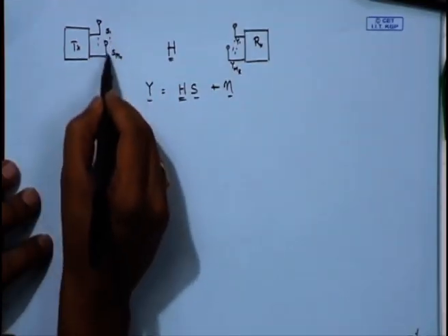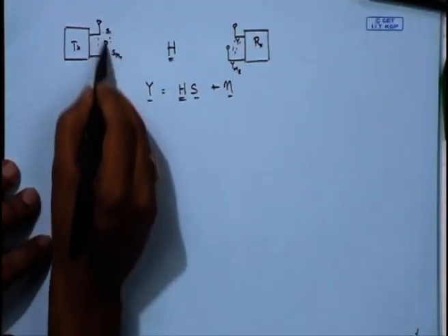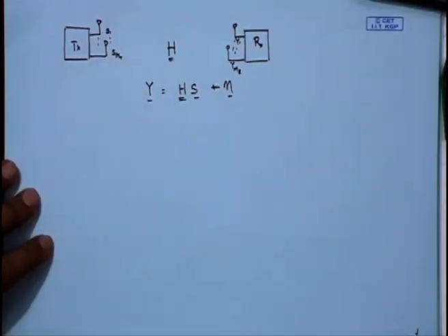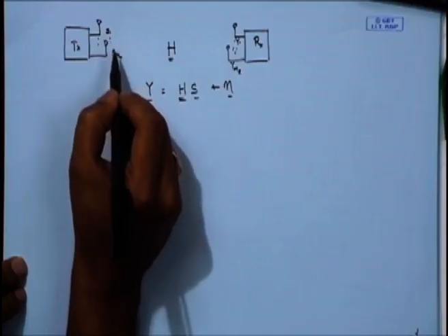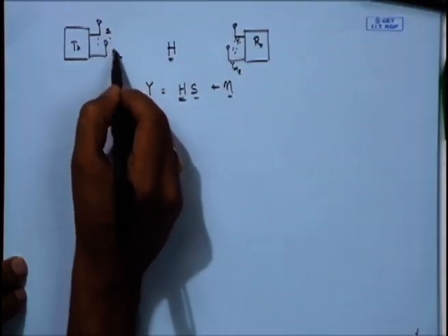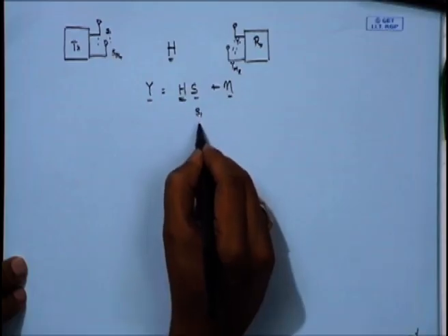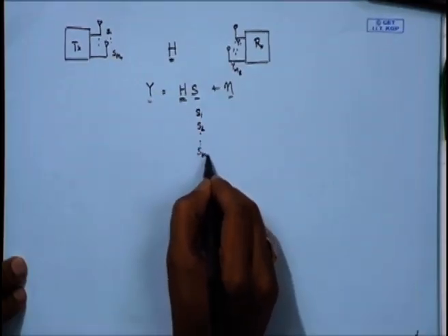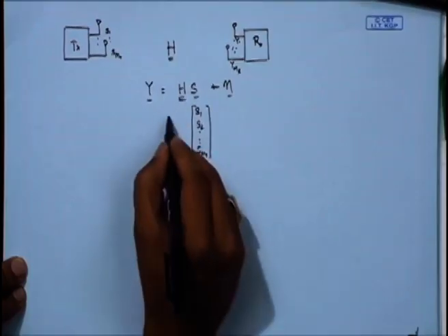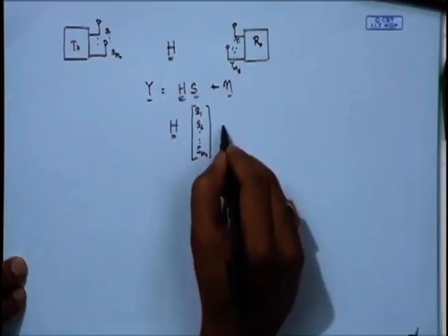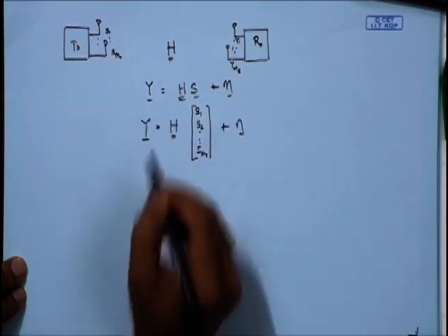So, if we are to transmit these signals, that means we have to put equal power. That is what the expression gave us. The result that we have got is basically putting equal power, but it never told us how you can send symbols across these parallel channels so as to achieve the result which we have shown. So, the mechanism that we are using is that we will be sending different symbols directly, S1, S2 up to S_MT, and we have this channel matrix plus noise across this.